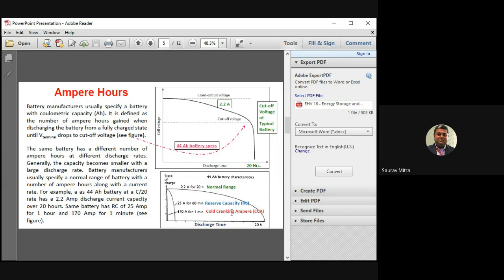Okay, so state of charge means from 100%, you should fall at lowest to 70%. As soon as it falls to 70%, you should put the battery on charge again. So here you are finding it has fallen to almost 70%, and after 70%, suddenly the battery voltage is coming to 0. So below there are 3 diagrams. First diagram, there are 3 graphs.